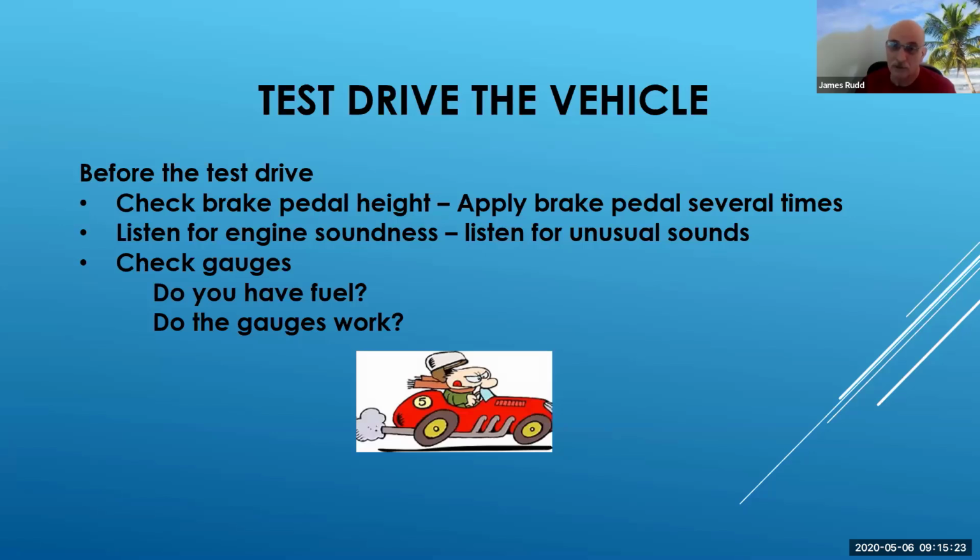But if there's no complaint about it, I do the pedal check, start the car up, and make sure it works before I go around the block, and listen to the engine soundness. If it's got some unusual sounds to it, and it sounds like the engine's coming apart, it's really not getting a test drive. And then I'm checking the gauges. One of the things I recommend you do right off the get-go, and we had a policy in a lot of the shops I worked for, is checking the fuel gauge.